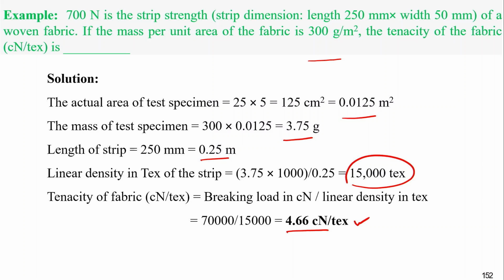So, till now we have calculated the strip tensile strength, but for our daily application another type of testing is required. So, grab test. In the strip form we test, but in actual use it is not gripped in that fashion.